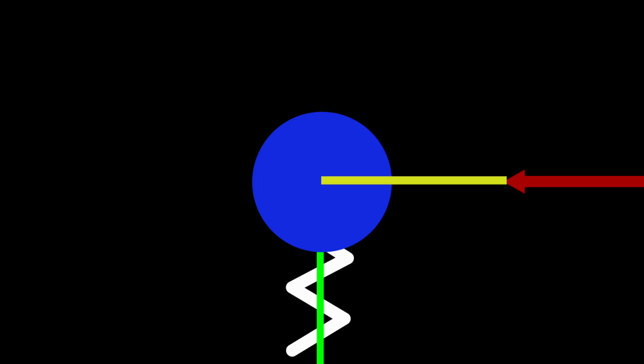For this instance, you see the suspension link, the yellow link, is straight horizontal, and then you have a force acting on it laterally, which is the red arrow. So think of that as the tire force going lateral. In this case, the end line is horizontal, transferring it straight to the chassis. And since it is horizontal, there will be no jacking. So the spring and damper do not move due to jacking forces.